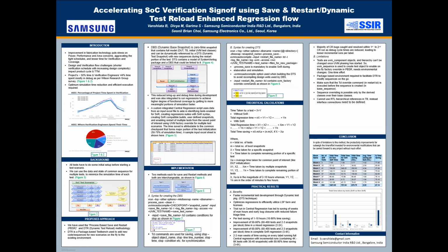Limited IP and VIP licenses and LSF queue is also a concern. It's quite difficult to keep up with the shrinking time to market goals when there's so much to take care of. Improved fab tech like the 7nm or the 4nm also puts stress on power, performance, and area concerns. This aggravates the tight schedules and allows for lesser time for verification and coverage. Although it's never possible to exercise 100% scenarios of an SoC for verification closure, it's pertinent that major bugs and loopholes are caught before a metal tape out.